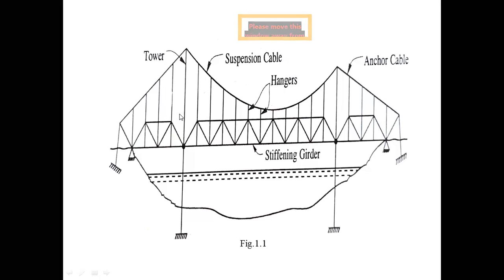Here I am showing one side; likewise there is another on the other side, with the road in the middle. A symmetrical suspension bridge, and the supports are at the same level. The cables are placed side by side at a distance of 6 meters, which is the road width. The span is 90 meters. The central sag YC, the lowest point of the cable, is 18 meters, and the supports are at the same level. Everything is given in the problem.